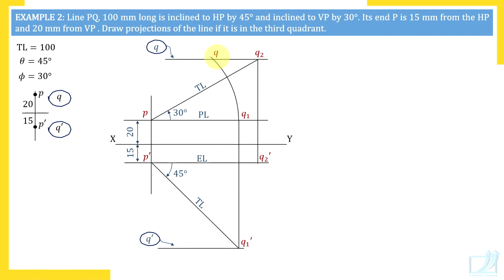Now once you get that point Q, remove that rough label. Now my suggestion is, even if there is nothing wrong in that, don't rotate EL. It is better to have a standardized procedure. When you use a compass, you get a new point. For example, here you got point Q. Now, unless there are horizontal and vertical lines through the newly marked point, don't use the compass. So, when you use the compass, use it once, get a new point, draw horizontal and vertical lines through that new point, and if required, use the compass again.